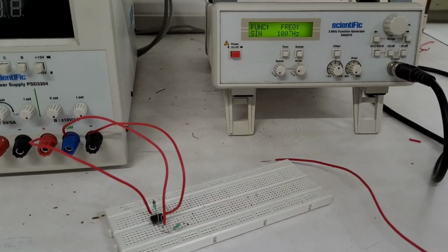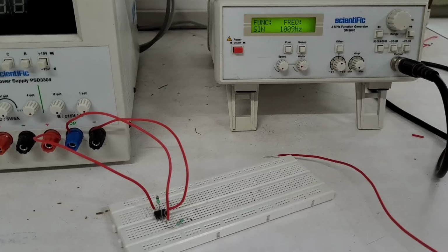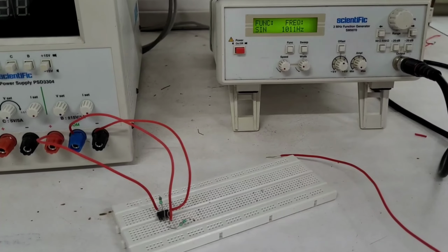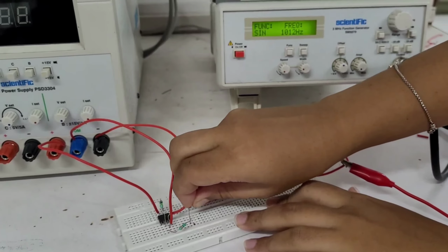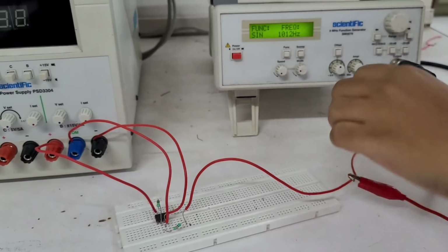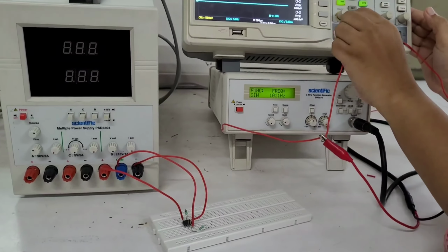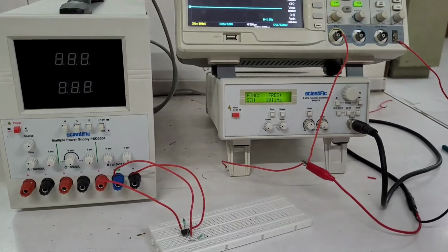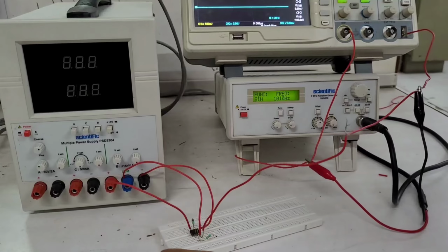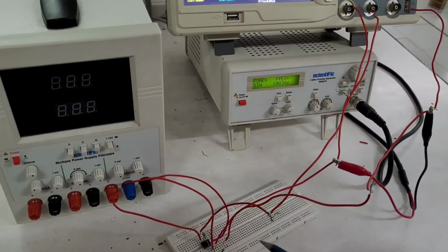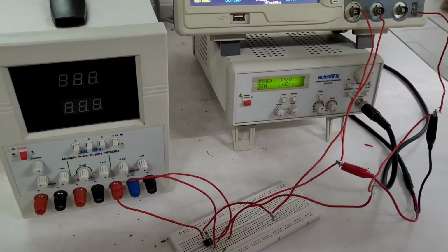Input signal is taken from function generator where sine wave is selected having frequency 1 kHz and 1 volt peak to peak. One of the input signals is fed to the input resistance and the other is given to channel 1 of DSO in order to see the input signal. The grounding is given to pin number 3. Output signal is taken from pin 6 and it is given to channel 2 of DSO.